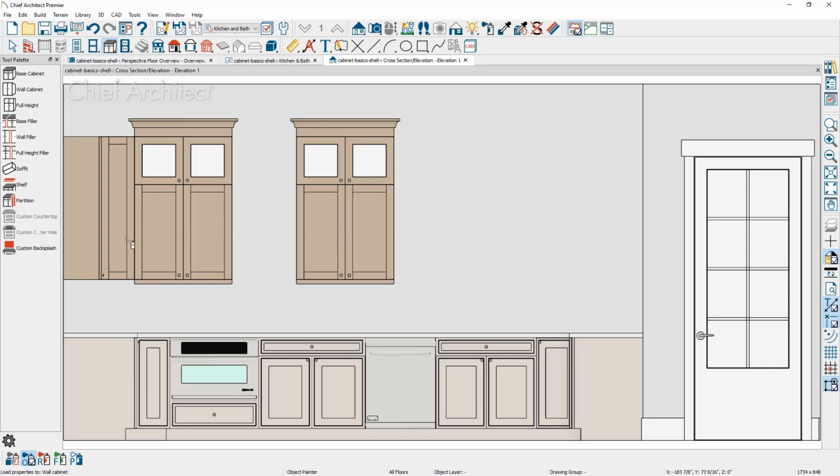What about the corner cabinet? If I click and apply it to this corner cabinet without making any changes, it will convert that cabinet to a regular wall cabinet without the corner. Let me press undo one time. The Object Eyedropper has scoping.